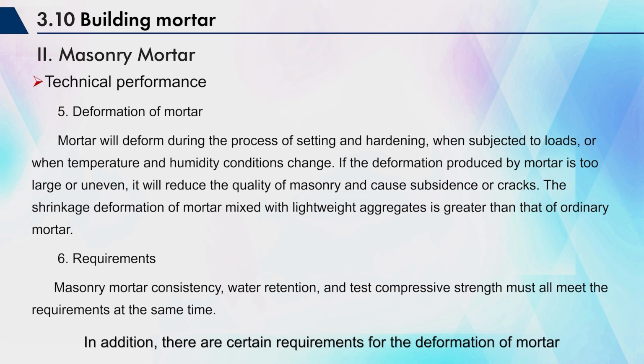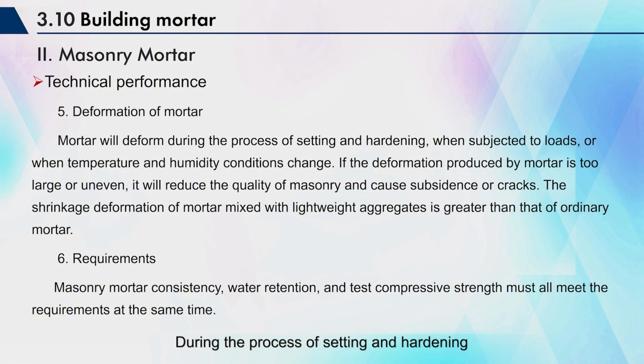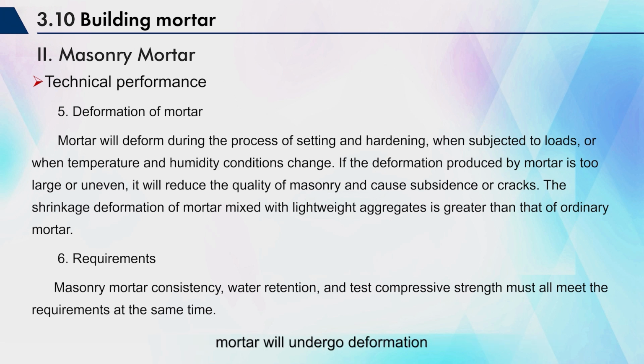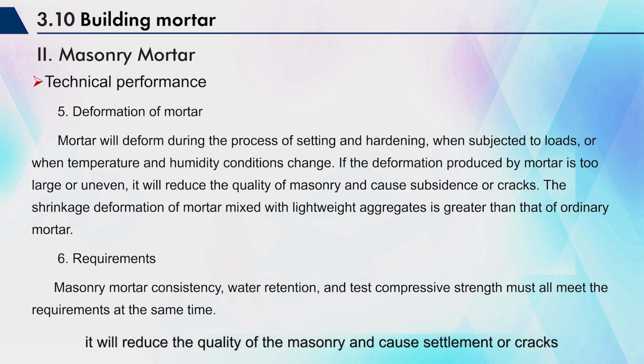In addition, there are certain requirements for the deformation of mortar. During the process of setting and hardening, as well as under changes in load or temperature and humidity conditions, mortar will undergo deformation. If the deformation of the mortar is too large or uneven, it will reduce the quality of the masonry and cause settlement or cracks.